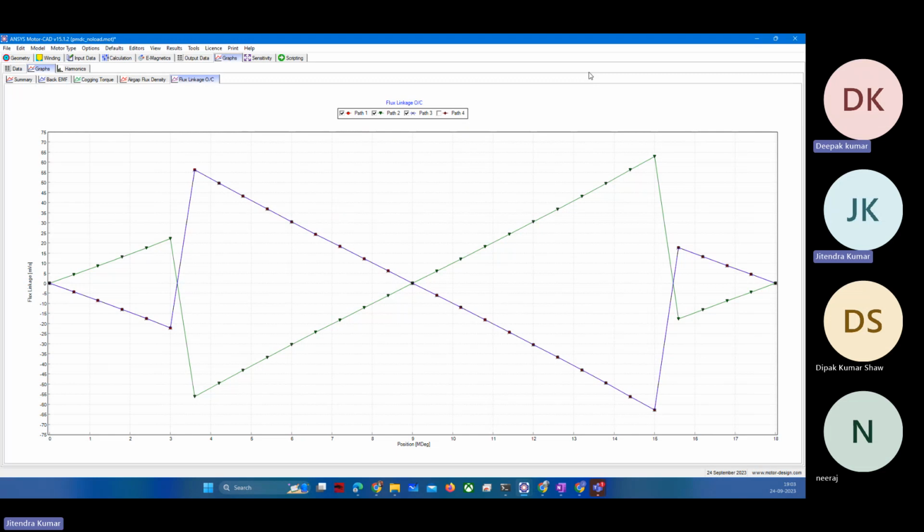Actually, see, I haven't seen those questions regarding which you are discussing. I guess you are discussing the current week's assignment. I haven't seen those questions since we are not allowed to discuss them, but you are going in a good direction that the direction reverses in case of motor and generator. In case of motor, I guess it is in the direction of rotation, and in case of generator, it is in the opposite direction of rotation. The shift of magnetic neutral axis to geometric neutral axis.